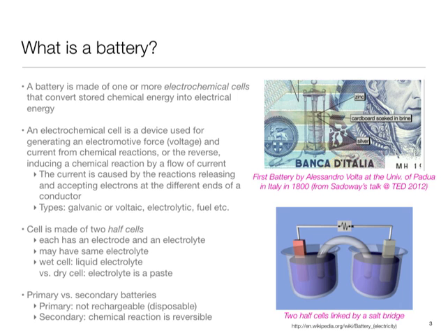under the hood, batteries are basically made of what are called cells, which are essentially little packages of some electrochemical material with a couple of terminals, anode and cathode, going back to your old chemistry. But the main thing is, at the end of the day, some chemical voltage difference gives rise to a potential, which is the energy that we draw upon. For our purposes, one of the things that matters is that batteries come in two varieties, primary and secondary. Primaries are disposable batteries, and secondary are the ones where we can reverse the process and recharge them also.